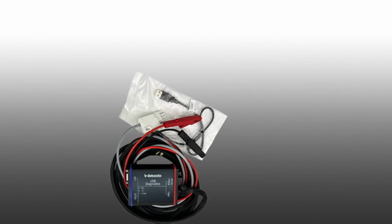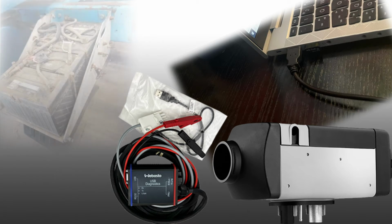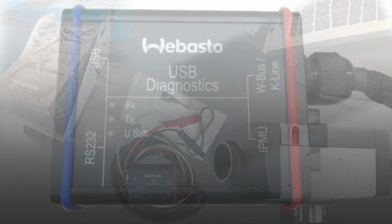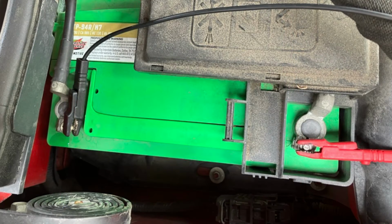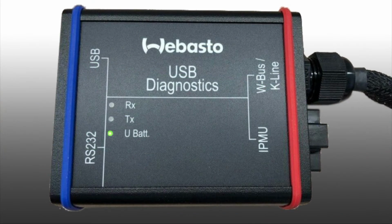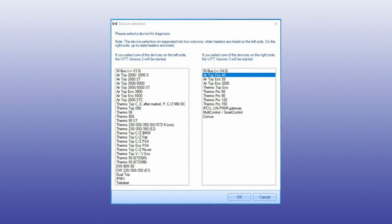Connect the PC Diagnostic interface to the heater, the computer, and the vehicle's battery. When you connect the diagnostic interface to battery power, you will see the UBAT light illuminate. The power for the PC Diagnostics must be taken from the same power supply that the heater is using. After the diagnostic interface is connected, it's time to open the software. One note on the connection before we begin.